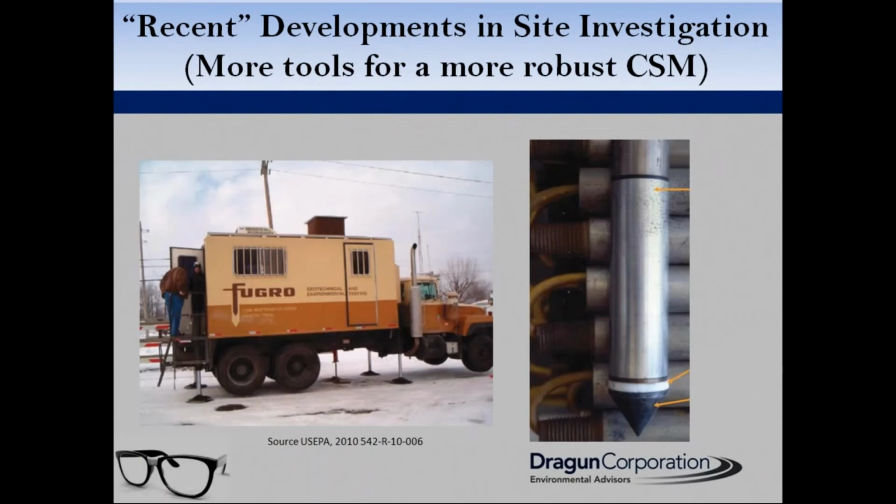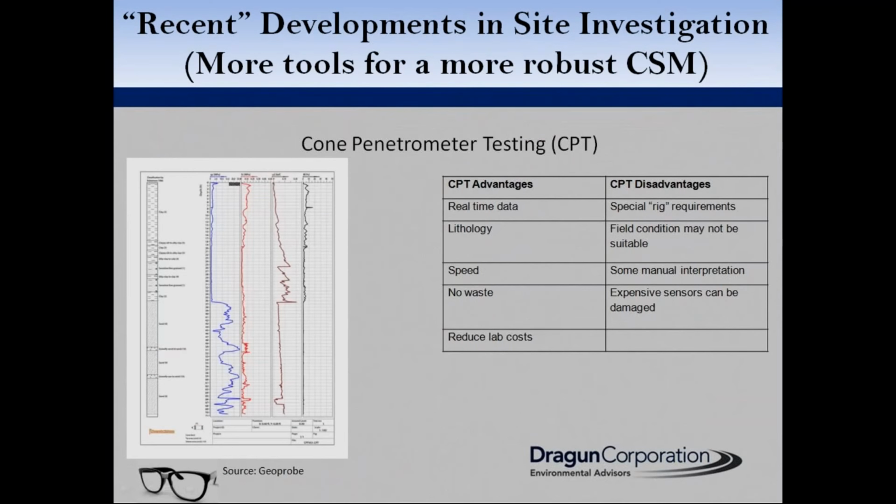The next thing I'm going to talk about is the use of the cone penetrometer testing tools. So these are downhole tools that are advanced. Instead of going out and doing your soil borings, you would advance this tooling string that has a sensor array at the base, and it's now a wireless method, and that array sends information to a laptop in which there's software which interprets the data as it's received.